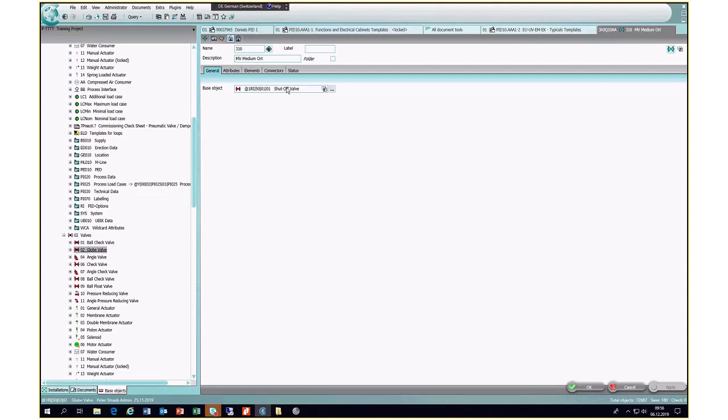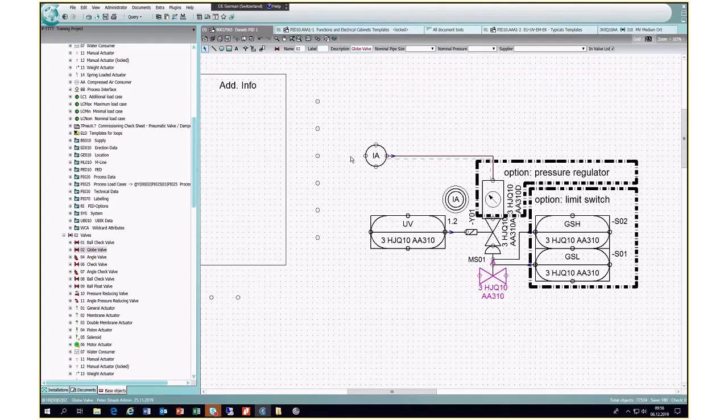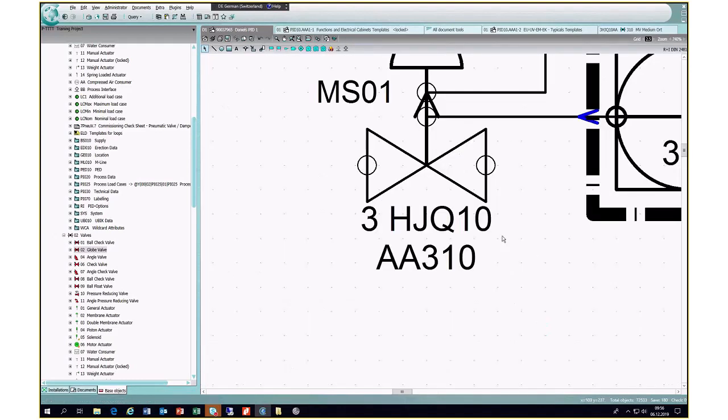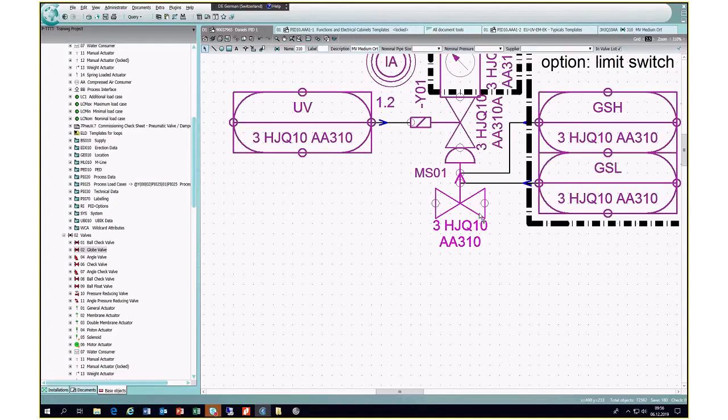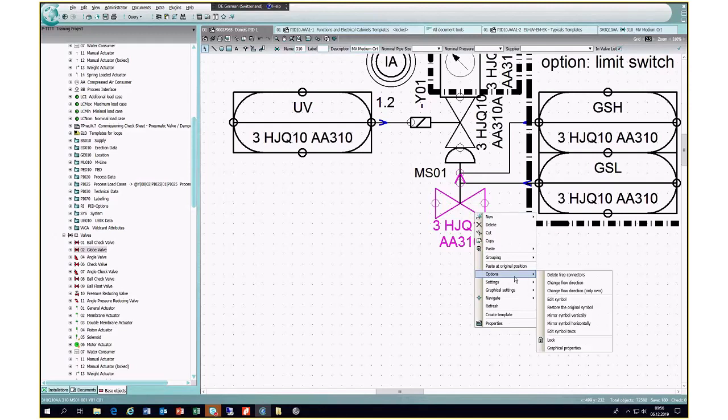Oh, so I'm just going to change it out like this by dragging and dropping this globe valve here, and you'll see that the path changed, the name changes. So I say, okay, that's fine, and then I take a look. And remember how that is when you change out an object like this. It doesn't always change, because if somebody had changed this object on this drawing, so what I have to do here is I have to click on it and say restore original symbol, right?